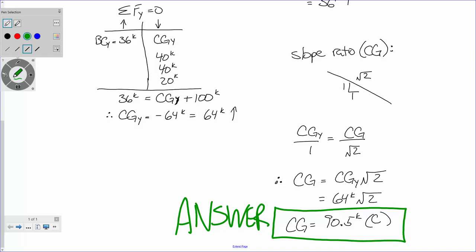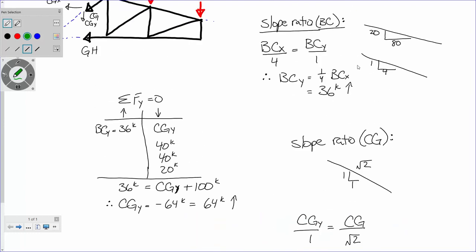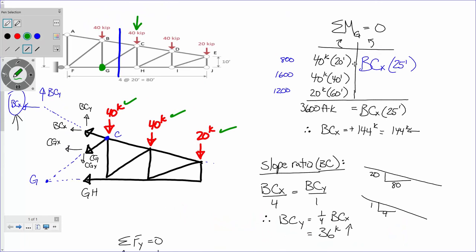But absolutely, if you want to go to the original truss and you can say this member has a rise over run of 80 to 20, so you can drag this out and say if you're dropping down 10, that's 40 feet, and then just sum moments out there, you're more than welcome to do that. And then you'll get the right answer.